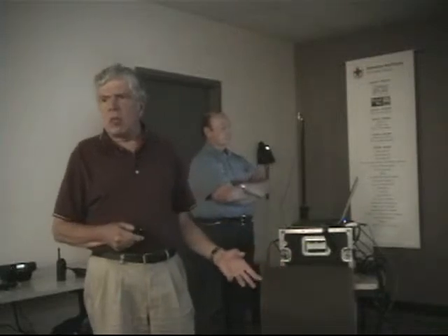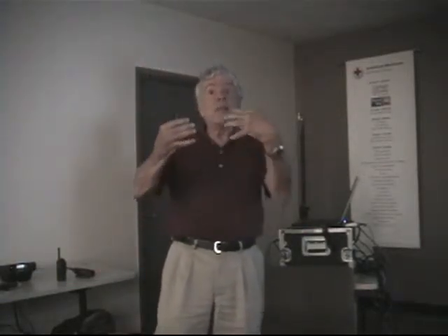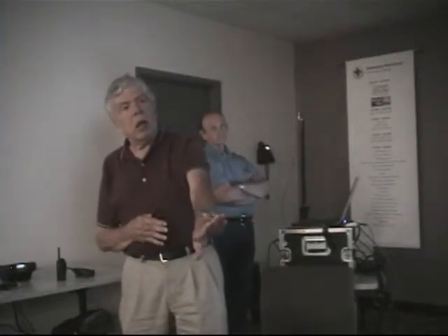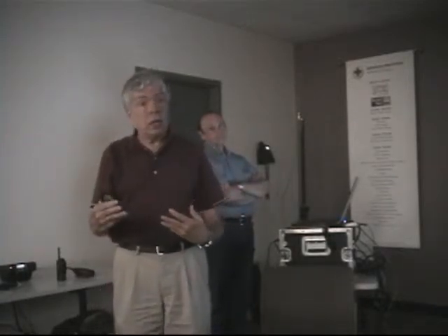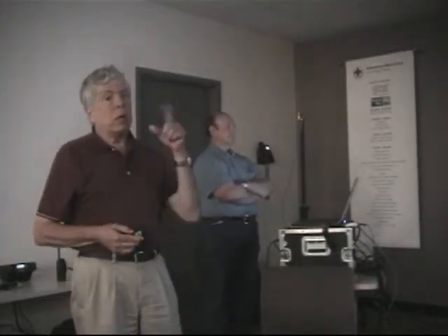Well, we can't test it the way we test a regular analog radio with SINAD, because of the way these voice coders work, they don't transmit tones. They recognize sounds, voice sounds and pitches, and they token that into a digital representation, transmit that across to the other end. Other end reconstructs the voice. So they don't deal very well with tones, although the latest versions have been specifically coded to allow you to transmit touch tone dial signals through there. They recognize and reconstruct that.